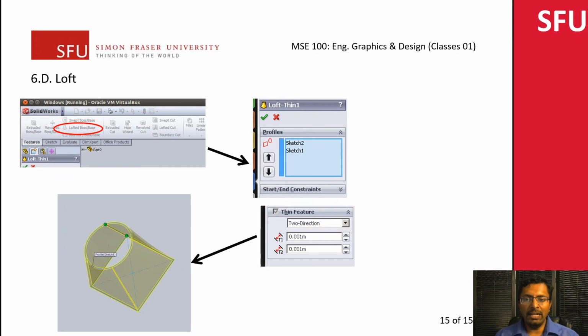The final shape we're going to look at is what's known as lofts. That allows you to transition between one shape and the other. An example would be the inside of your ventilation system, where you go from a rectangle to potentially a square and then maybe an offset circle. That's where lofts would be useful. To do the lofts, you'd use the loft function. You'd need to define two of those profiles, so let's see how that works.